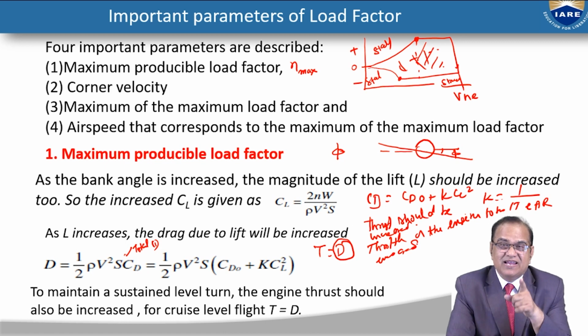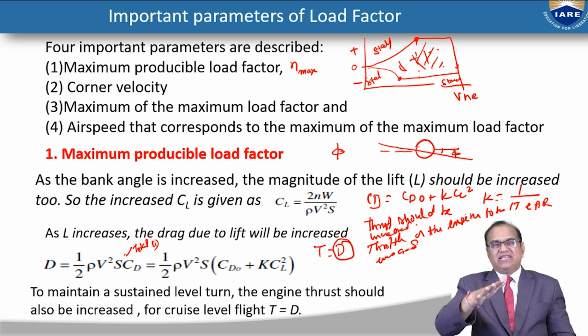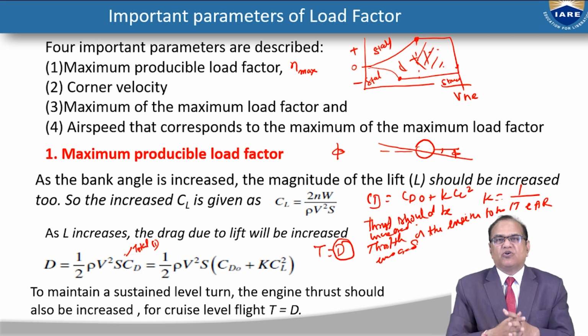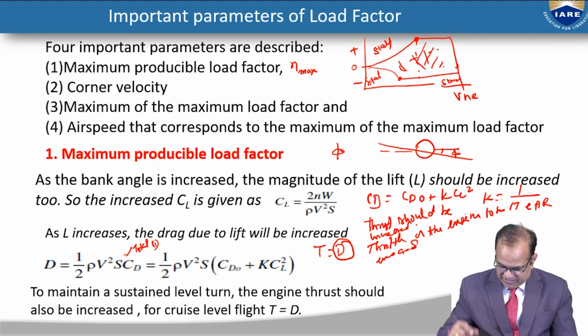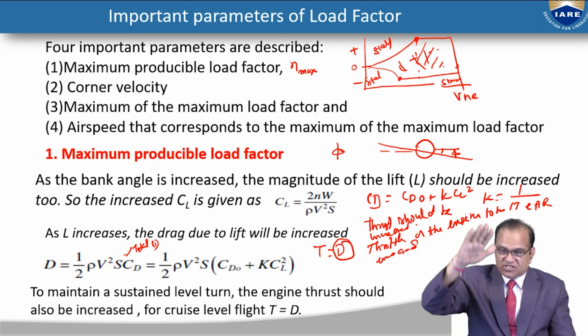So the bank angle makes sure that drag is increased. Due to the increase in drag, we need more power. So as we are flying in the banking zone, we have to ensure that the power of the engine is increased. Otherwise, it will start sinking down.